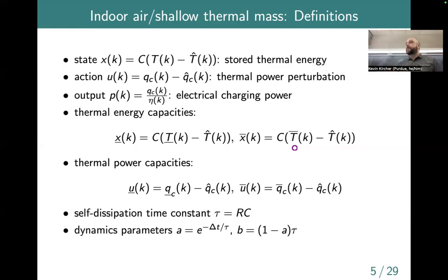Yes. So the QC min, QC max, that's based on what? So QC would be the thermal power that's delivered to the space. For this room, that'd be what's coming off of the radiators. And the min and the max of that are basically how much heat you can get out of that, the heat exchanger area, how hot the working fluid is, stuff like that. And the nominal value Q hat, again, is like if you kept the building exactly at the profile T hat, then you would use Q hat thermal power.